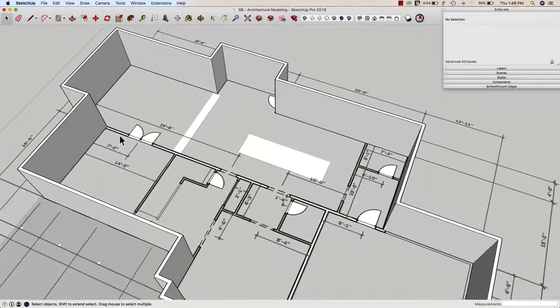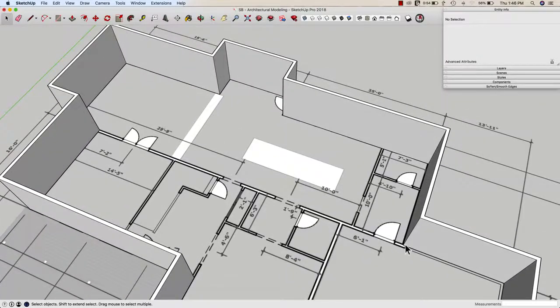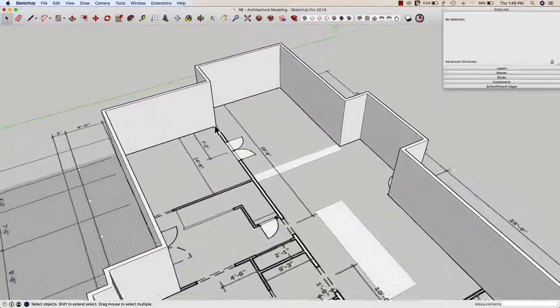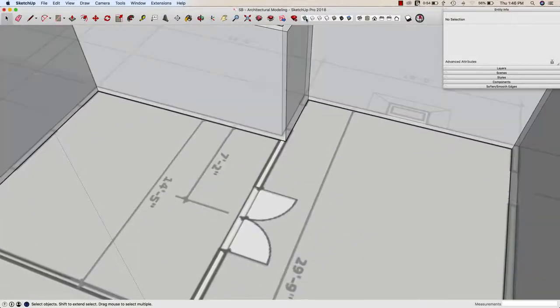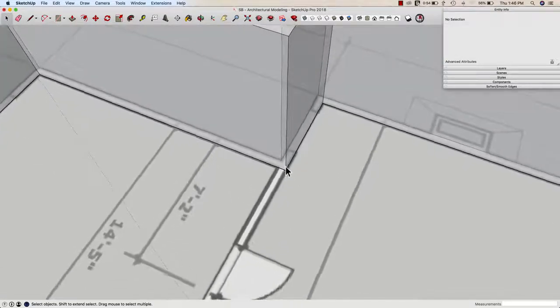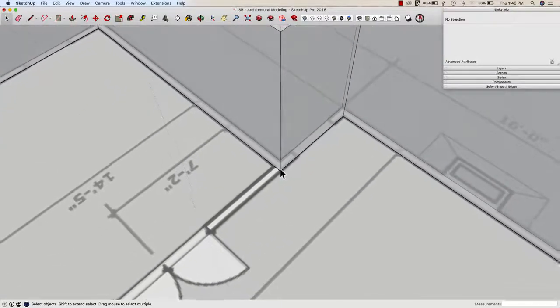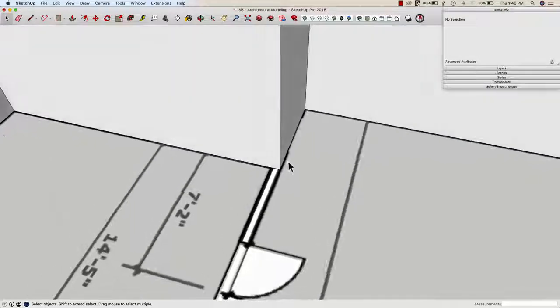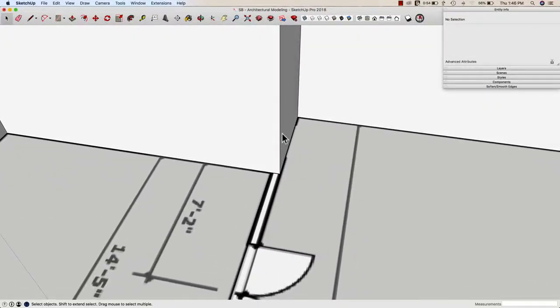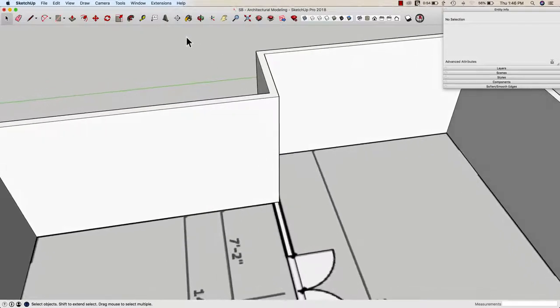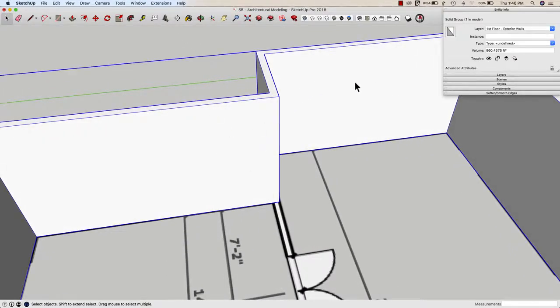So I'll go ahead and start with this big wall right down the middle. See right here? It looks like it lines up with this corner. If I snap X-ray on and off, I can actually look at where that other wall lines up in reference to the image. Yeah, I feel pretty confident saying that I should have a wall coming right up this corner flush with this exterior wall. Remember, all my exterior walls are grouped, so I can't mess with that geometry.